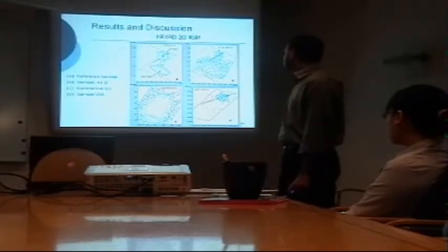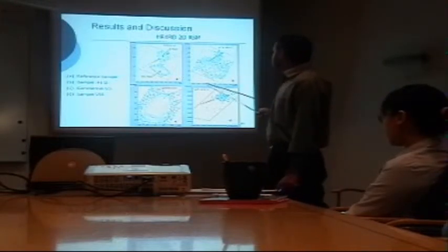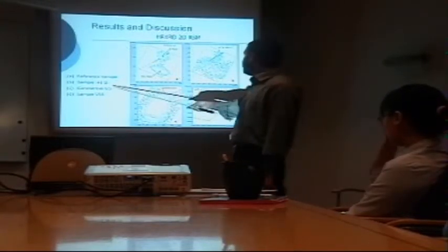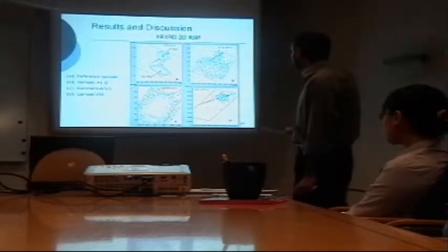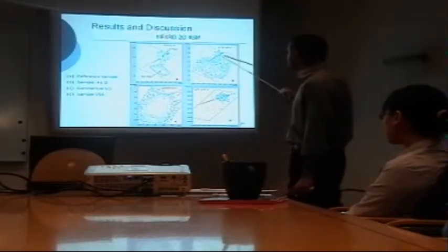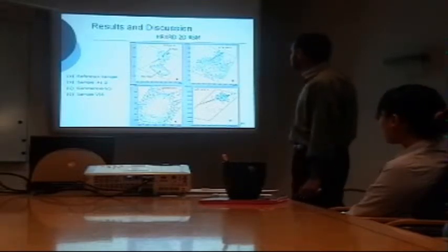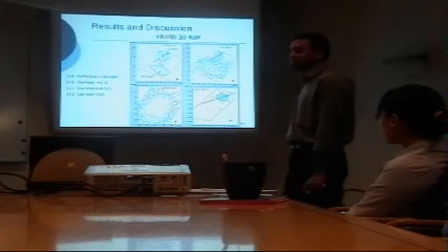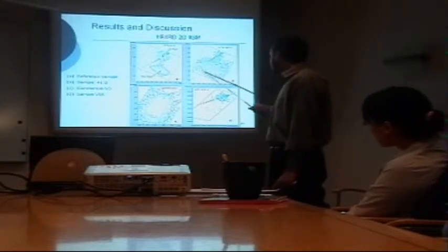In figure B, which represents sample V41D, which has a very low temperature growth step at 150 degrees centigrade, the surface is relaxed, but the silicon germanium layer quality is not good because the silicon germanium peak is quite broadened.